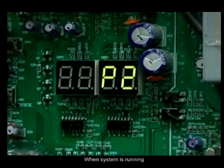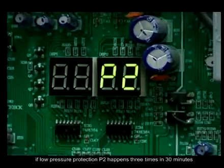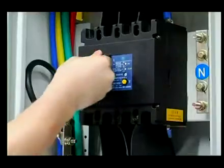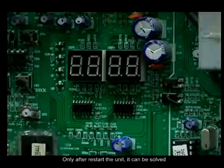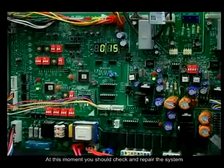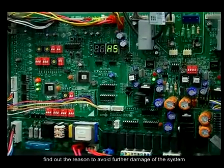When the system is running, if low pressure protection P2 happens 3 times in 30 minutes, the system will be locked and display the H5 malfunction code. Only after restarting the unit can it be solved. At this moment, you should check and repair the system. Find out the reason to avoid further damage to the system.